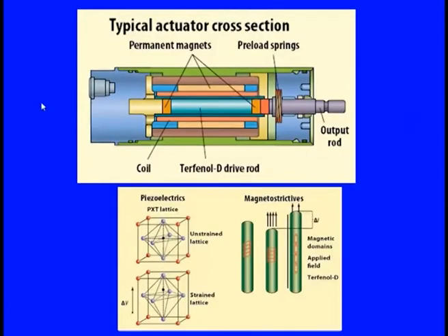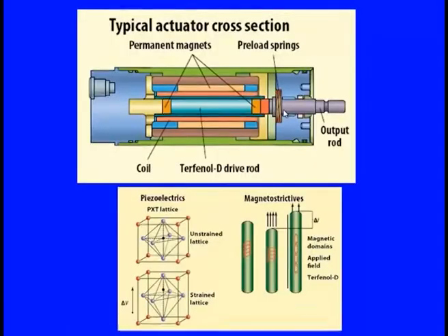So, you see here we can exhibit right from 60 microns shape change in cobalt to 2000 microns shape change in Terfenol-D. So, you can see that we have a clear Terfenol-D drive mode here, and then the coils are there through which we can straightaway put together the part, and then the permanent magnets are there. This is the preloading part, because we know that if we want a significant deformation or shape change, certainly the preloading springs are always required, and this is my output.